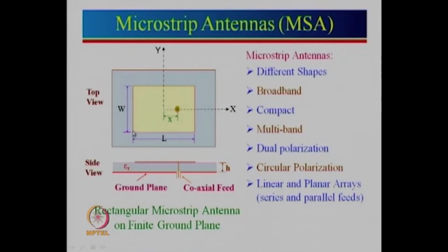So, current will be 0 here, current will be 0 there. The field will vary from 0 current to the maximum current and go to 0, because that is what makes the half waveform. What about the voltage? Voltage will be maximum here, then voltage will go to 0, and then to the minus maxima. It will start from plus, go slowly to 0, and then go to minus. So if the voltage is maxima, current is 0.